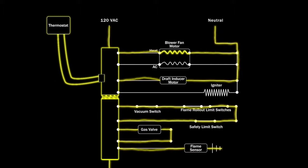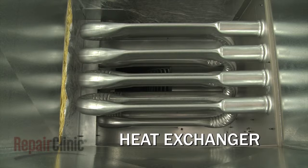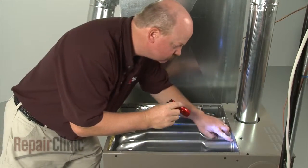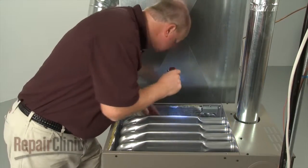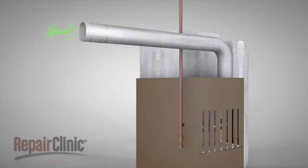The blower fan draws air through the return vent, blows it past the heat exchanger, and forces it through the home's venting. Over time, heat exchangers may crack and cause carbon monoxide to leak into the air being circulated throughout the home. Since carbon monoxide poisoning can result in death, we recommend that only experienced professionals repair or replace damaged heat exchangers.